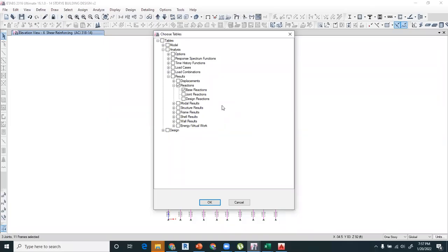जिस ऑफिस में मैं काम करता हूँ सर, जो मेरा सीनियर है वो कहते हैं कि रिइंफोर्समेंट कम नहीं करना, लेकिन बार का जो साइज है, मतलब नंबर 6 यूज़ किया, तो जो नेक्स्ट स्टोरी होगा उस पर नंबर 4 डाया वाला बार देना है. ये जरूरी नहीं है कि हर जगह ये इम्प्लीमेंट होगा. फॉर एग्जांपल नीचे से आपके पास 24 आ रहे हैं, ठीक है, और आपको ऊपर रिक्वायर्ड 24 नहीं है, आप 20 देंगे एज पर द साइज ऑफ द कॉलम, तो आप 24 के बजाय 20 दे सकते हैं.